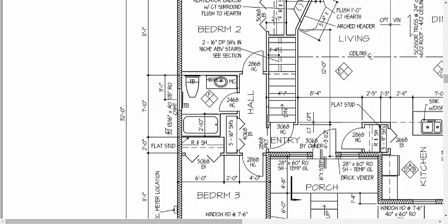So something new is this 32 and so on by 40 and so RO. And then there's a CSMT. Well, what all this means here is that's the description of this window. So right here is a window in the wall, and that is a type of window that's called CSMT or casement window. And a casement window you guys are all familiar with, but that is a crank window. So the kind that you crank and it pivots on the side, it opens up, right? That's called a casement window.